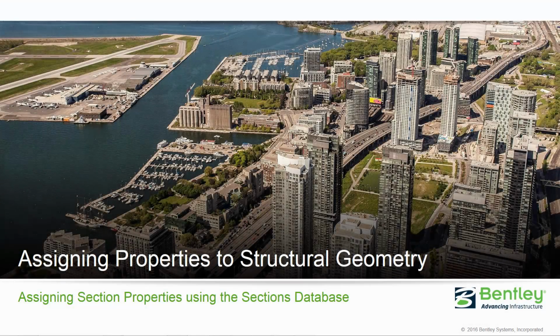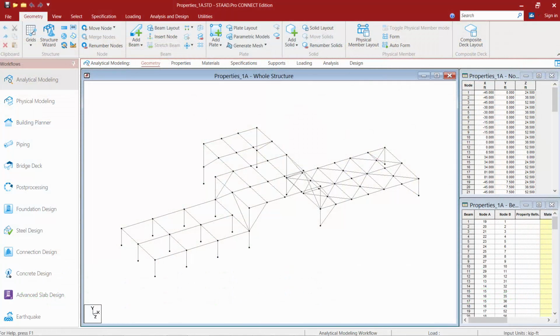Welcome to the Bentley Systems training course where you will learn how to assign properties to structural geometry. In this video, we are going to be focusing on assigning section properties to steel members using the standard sections database. We will now turn our attention to our sample model, which has already been started in STAAD.Pro CONNECT Edition.